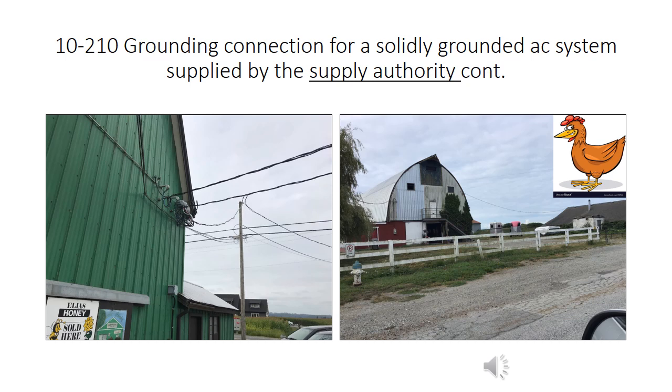In both photos, neutral support cable is installed overhead from an electrical room to an outbuilding. Neutral support cable does not contain a bonding conductor. Neutral support cable normally contains either 2 or 3 ungrounded conductors and a bare identified conductor. Therefore, regrounding was re-established at an outbuilding.